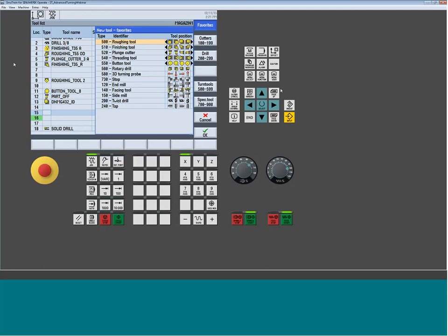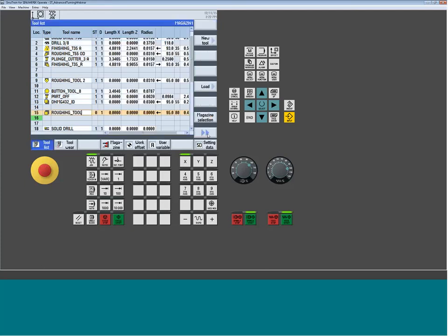Okay. So we're here. We're building the tool, and I was just showing the 8 different orientations on any given tool. So when you pick that new tool, the first thing we're going to have to choose is the way it sits, and this first one is always going to signify an OD tool. From there, once you pick the appropriate tool orientation, simply hit OK, and now you get the option of giving it a name. So let's say I wanted to use more of that ISO standard for my name. I'm going to create a CNMG